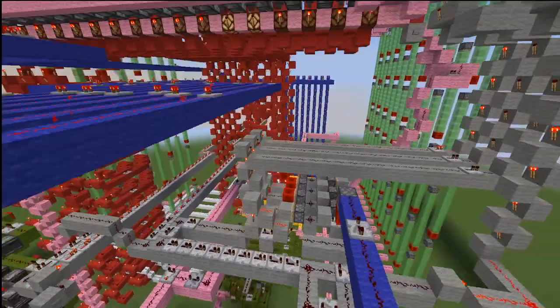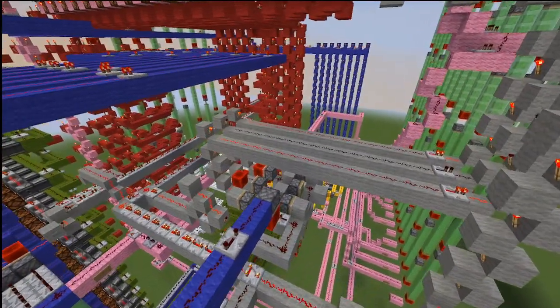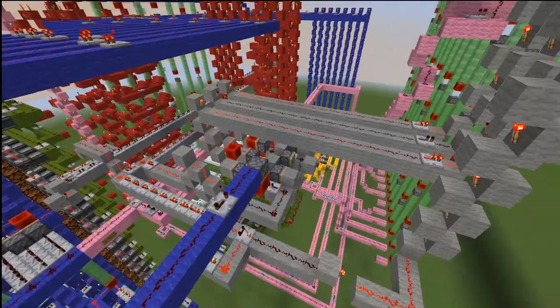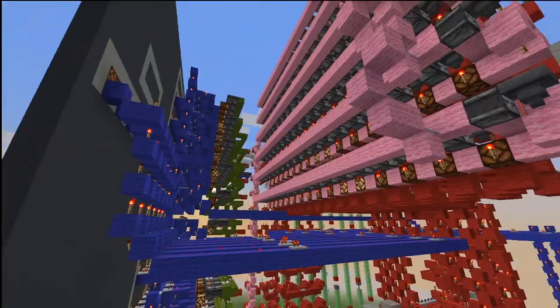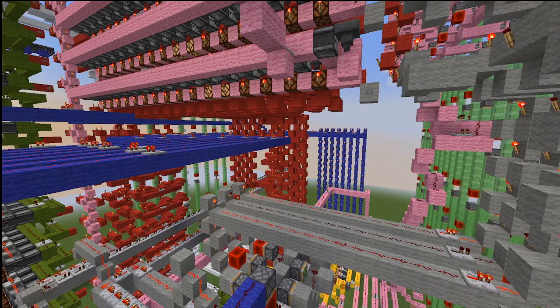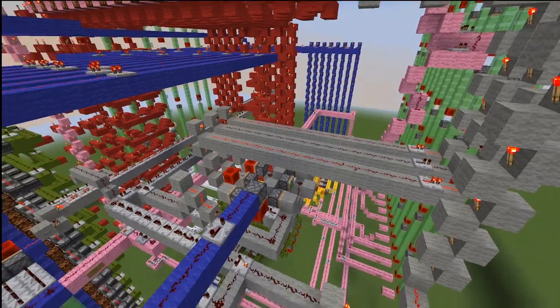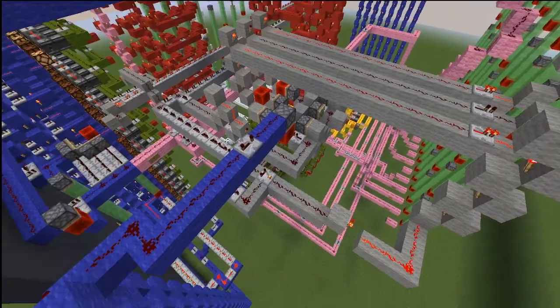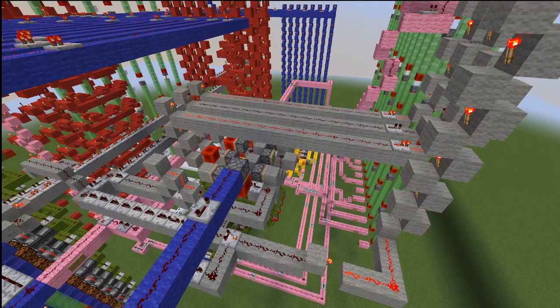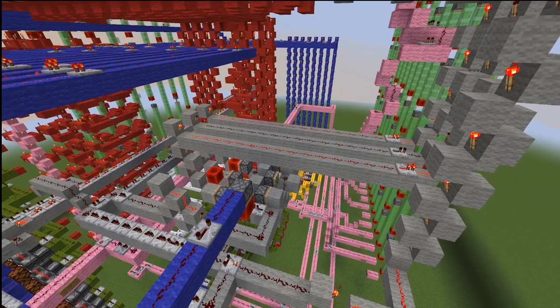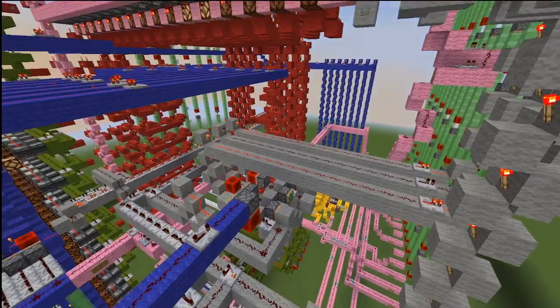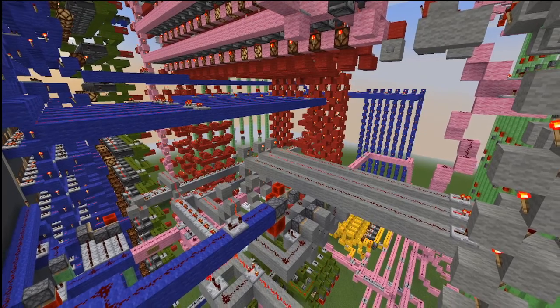So we just have to wait for a while, quite a while actually, because this is the shortest macro instruction in terms of how many macro instruction sequences it is. The only other shorter one is a halt, but obviously you don't have to wait for a halt because the clock will stop. So when you have a no operation, it's kind of just sitting here waiting and waiting and waiting until your next instruction can execute.